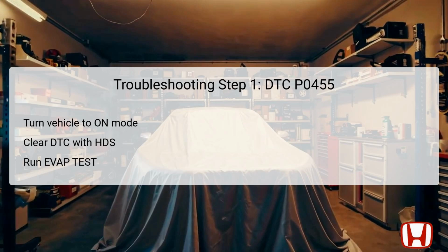This functionality is important as it checks the overall system performance and helps determine if the system is currently functioning without issues. If the test indicates everything is fine, it may suggest an intermittent failure requiring further investigation of the electrical connections at various sensors or valves in the EVAP system.